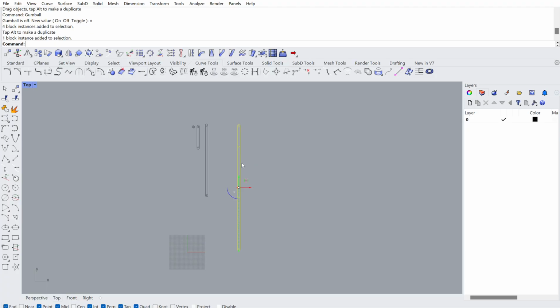The other thing is that if you have grouped geometry, it's going to come in as what's called a block instance. Rhino does have grouping. Block instances is often how it deals with groups from other programs. So if we want to unblock these, we do a specific type. I think regular explode works. Yeah, regular explode works. You can also do explode block, and then select the blocks to explode.